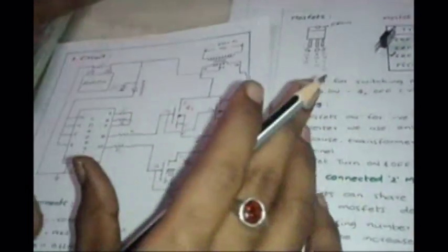Generally we use 2 MOSFETs. You may have a doubt, why should we use 2 MOSFETs? Why can't we use only a single MOSFET? We use 2 MOSFETs connected in parallel, so they can share the current, so that whenever you place a load, the MOSFETs don't get any strain. If you increase the load, the MOSFET doesn't get damaged. By increasing the number of MOSFETs, you can increase the wattage of an inverter. You can connect 3 MOSFETs in parallel or even 4 MOSFETs in parallel. By that you can increase the wattage of an inverter.